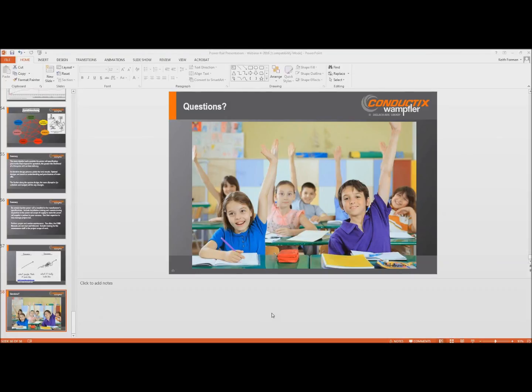Recommended gap between Power Rails, and I'm assuming you mean two Power Rails on the same polarity. So it really depends on the collector shoe. A good rule of thumb is that if the collector shoe is articulated, imagine a shoe that has a post supporting it, and that collector shoe can rotate on the end of that post, the gap obviously can't be any longer than half the length of the shoe. Otherwise, that collector shoe will tip into the gap. So, in fact, that's why ideally collector gaps are at a bias.